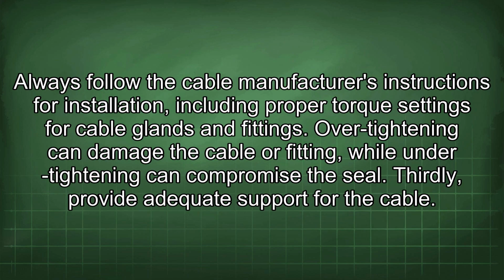Secondly, follow the manufacturer's instructions for installation. Always follow the cable manufacturer's instructions for installation, including proper torque settings for cable glands and fittings. Over-tightening can damage the cable or fitting, while under-tightening can compromise the seal.